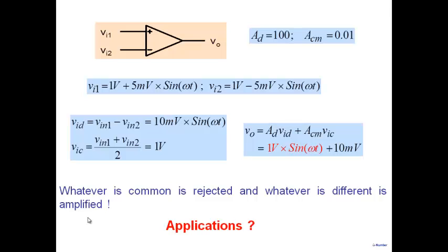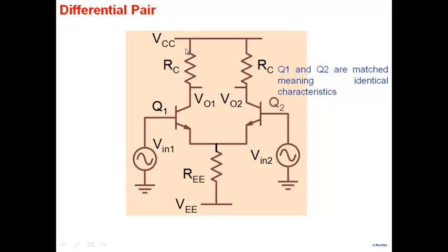All right. Is this amplifier useful? Can we think of applications for such an amplifier? All right. So there are many, many applications. One is, of course, note that this differential amplifier that we are building in the manner that I've indicated solves a biasing problem. We don't require any coupling capacitors, and we can bias the amplifier and apply the signal also.